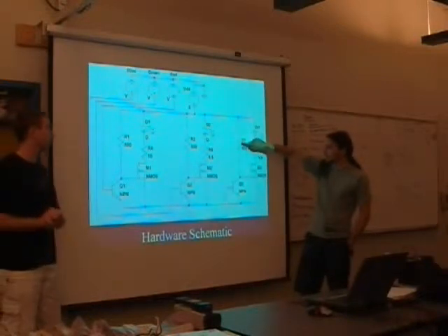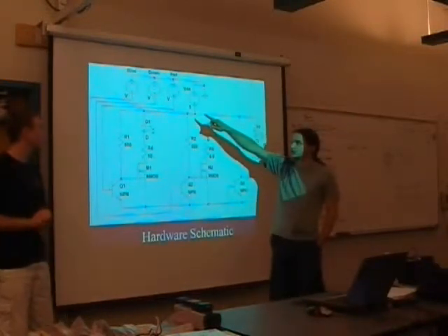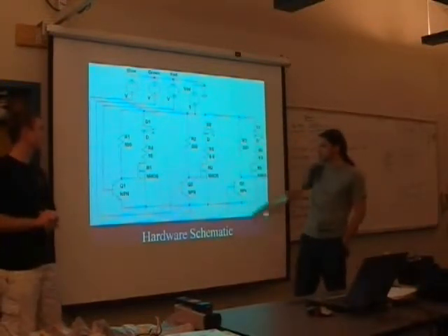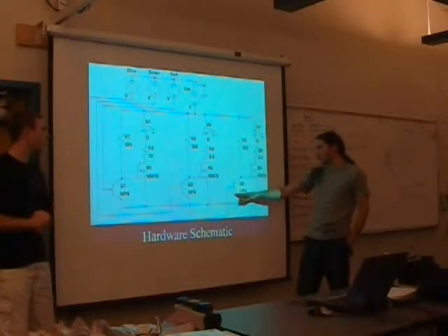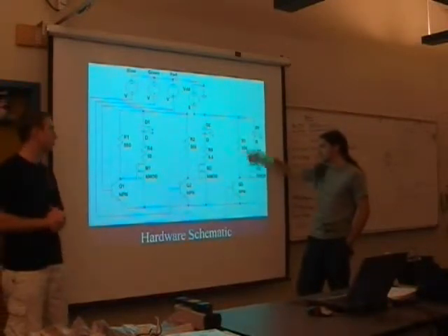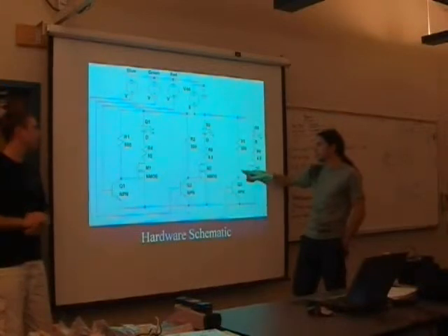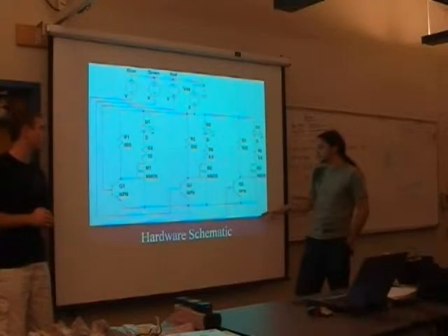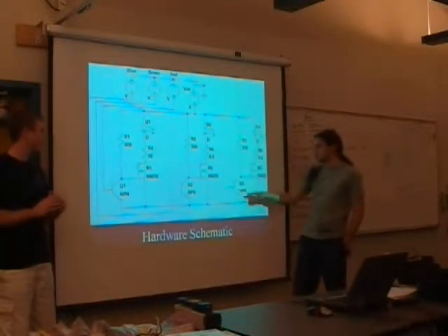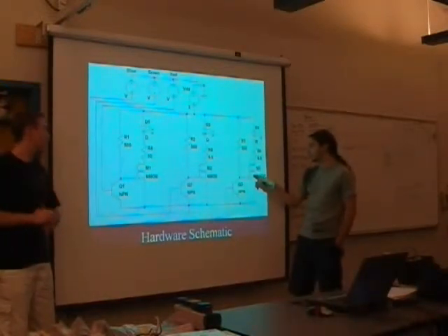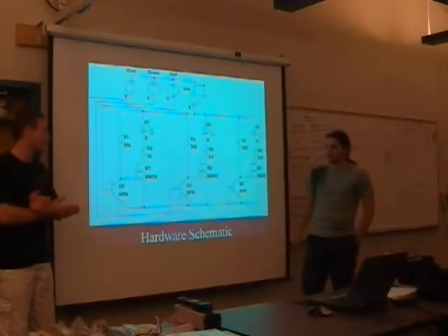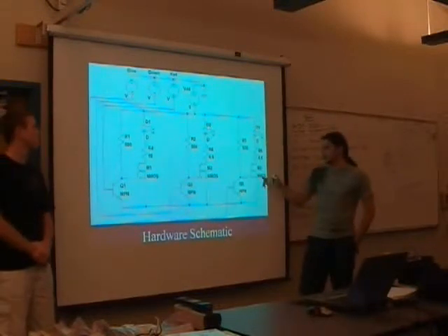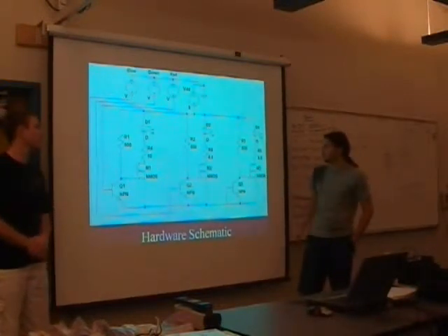So what we did instead was we used these external BJTs as basically an amplifier, and they're connected to these pull-up resistors. When you get a low signal out of the pulse width modulated control signals, that turns off this BJT, so there's no current flowing through here, and the gate is connected to VDD. When you have a high signal, it turns this on and grounds the MOSFET gate. It's all flipped, so a high from the controller actually turns off the LEDs.